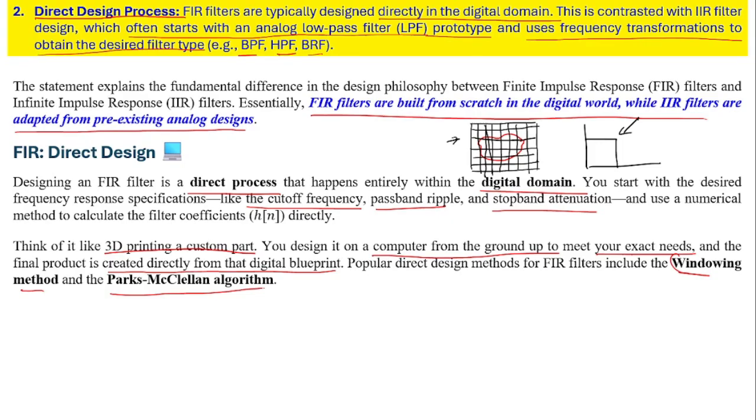Yes, so what is happening? What is happening to the distance? Where does the zero come from? And the same distance everywhere, one, and the value is one. So with the zero placed at some distance, whatever the magnitude is modified, it is due to the placement of the zeros. And poles, since they are sitting at the origin, the distance is one to each and every frequency component, so they are not playing any role over there, right?